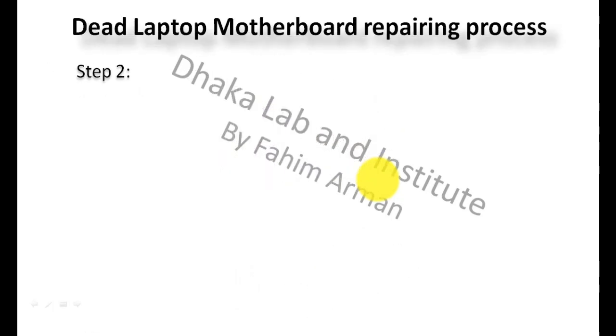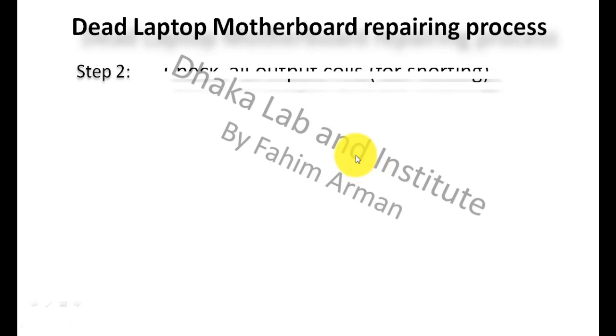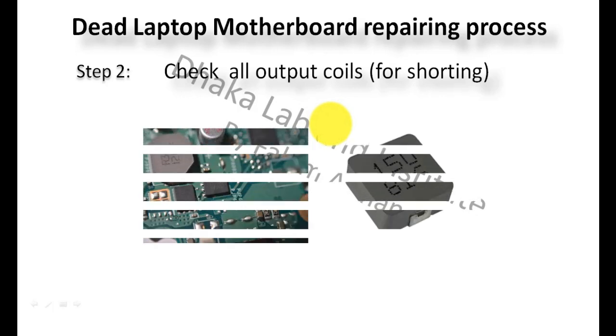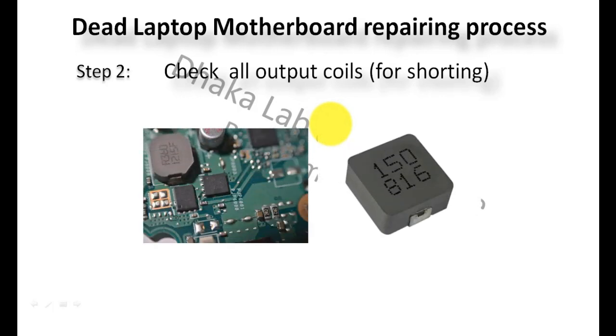Step 2. First, disassemble your laptop and bring your motherboard to your table. Check all output coils for shorting. You may say how to check.